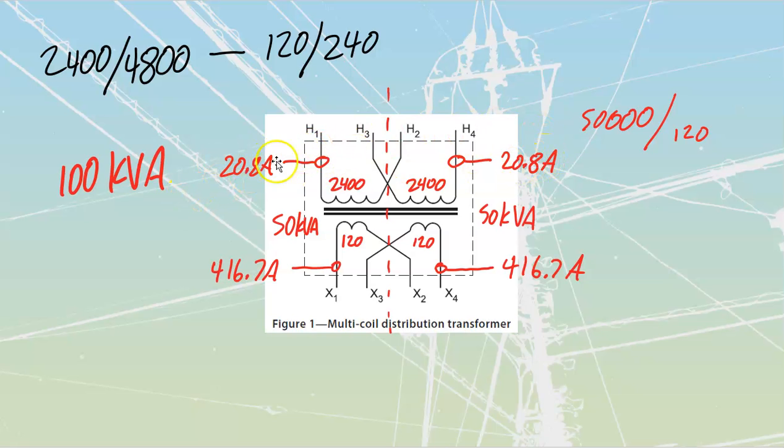Remember how I said before we do connections, let's just make sure we get all these current values so that we know we're good to go. Tell me, if I series connect these two together, I could feed in a total of no more than 20.83 through here, and feed out no more than 20.83 through here, right? So I would not be overdoing it with that winding. That winding would be completely fine for developing that amount of kVA.